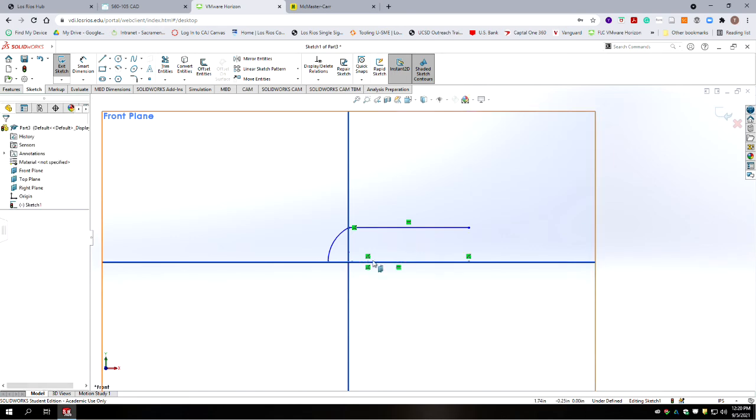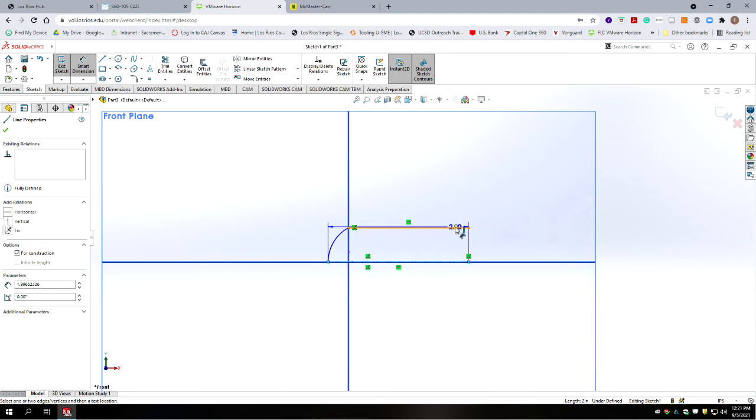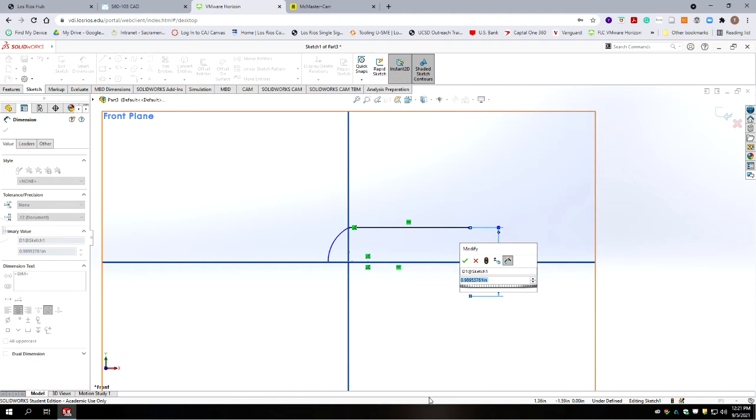Okay, so I've just made it horizontal, and it terminates the same point as the end of the part. Now there's a handy thing with dimensioning in SolidWorks. If you're doing something you know is going to be revolved around a center line, you already have that made, you can select the center line, select your entity for a radius, and if you drag your cursor down below, it assumes you want to put in a diameter number. But you have to have the center line involved. So we can go ahead and put our diameter in just like the drawing shows.